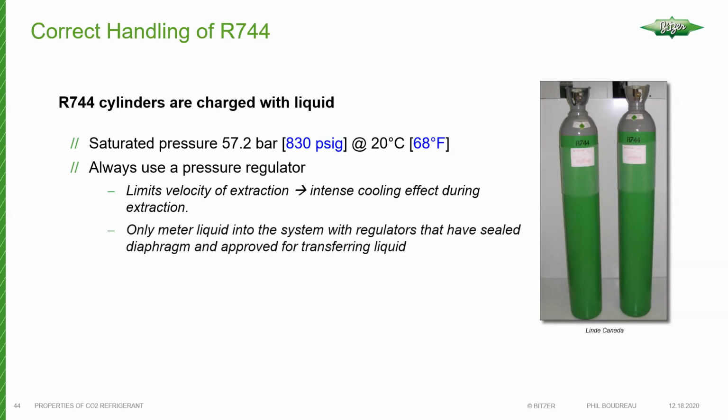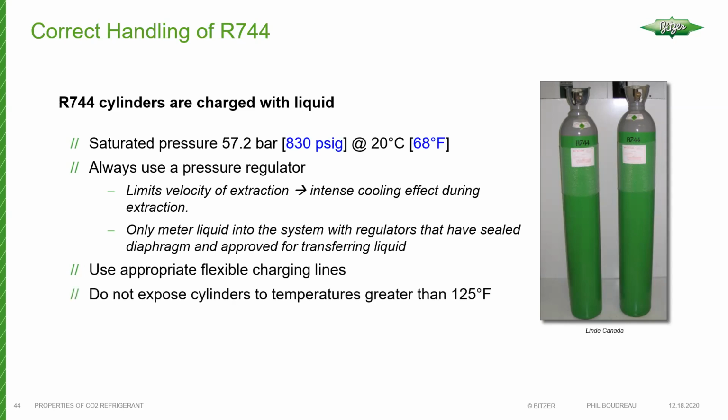We want to make sure that the gauges are appropriate for use with CO2 as well, so that they have diaphragms that are sealed against liquid, so you don't have gauges that trap liquid and things like that. But there's gauges that are specific to CO2, and of course you just want to make sure that you use those. And of course, we want to make sure that we use flexible charging lines. For sure, it's kind of like in the 410 days, you wouldn't, or shouldn't, take your existing hoses and gauges and just apply them.